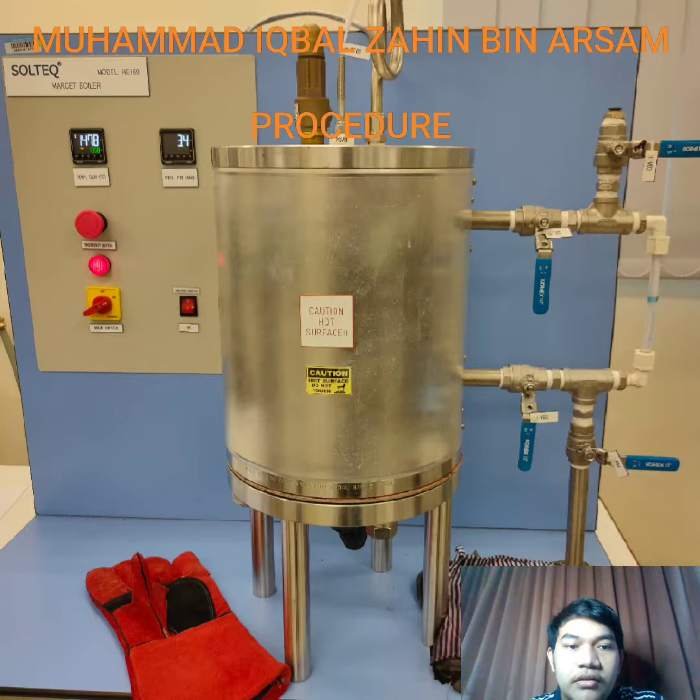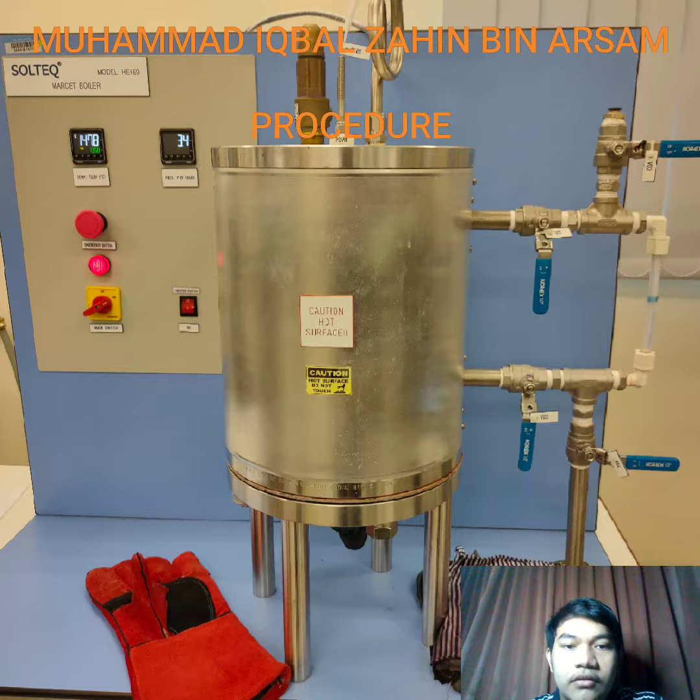Third, set the temperature controller to 185 degrees Celsius, which is slightly above the expected boiling point of the water at 9.0 bar. Next, open the vent valve V3 and turn on the heater. Next, observe the steam temperature rise as the water boils. Next, allow steam to come out from the valve V3 for about 30 seconds, and then close the valve.